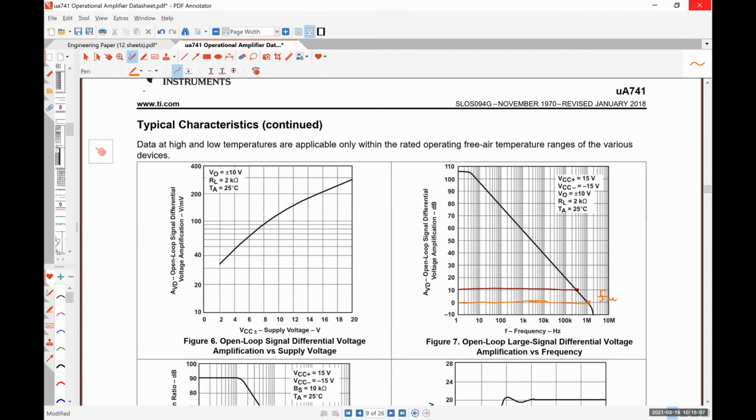So if you have an op amp with an open loop gain of a couple of 100,000 like this guy, and you want a closed loop gain of 100, which would correspond to, let's see, 0, 10, 20, here's 40, your bandwidth is around 10 kilohertz. Really easy to interpret this style of graph. So any questions on the finite bandwidth of an op amp? Yes.